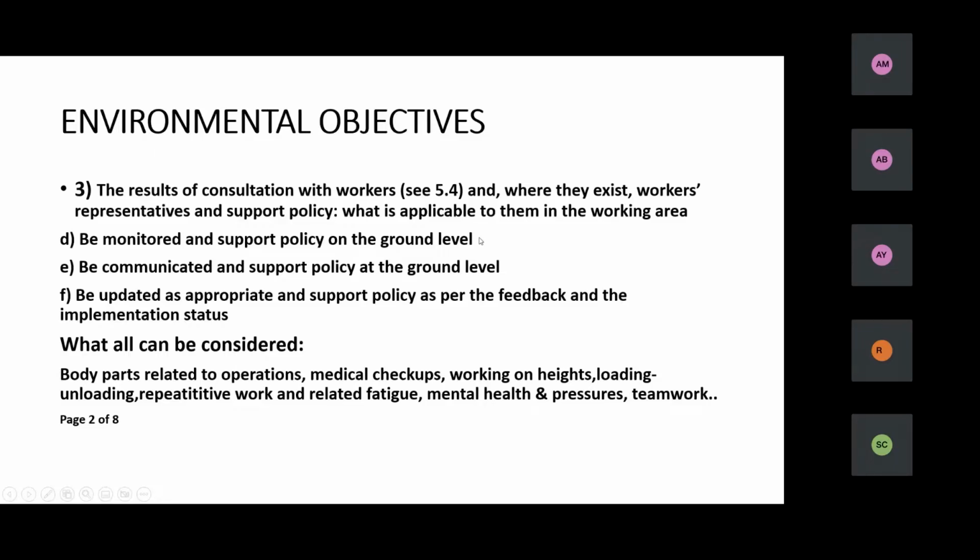When we are in a production situation, the machine is running, a grinding operation is going on. So the safety policy indication is there to see that when a machine is operating, the operators, the nearby visitors, the travelers are kept safe against those chips or the grinding things coming out of it, the powders. So how will the objective work on the ground level? We need to take care that yes, we have the safeguard, we have the belts under control, we have the speed under the tolerance level, we have the windows closed, we have the wheels changed in time, we have the operator trained to see that yes, he is running it by following the checklist of the grinding wheel operation to make it a safe operation.